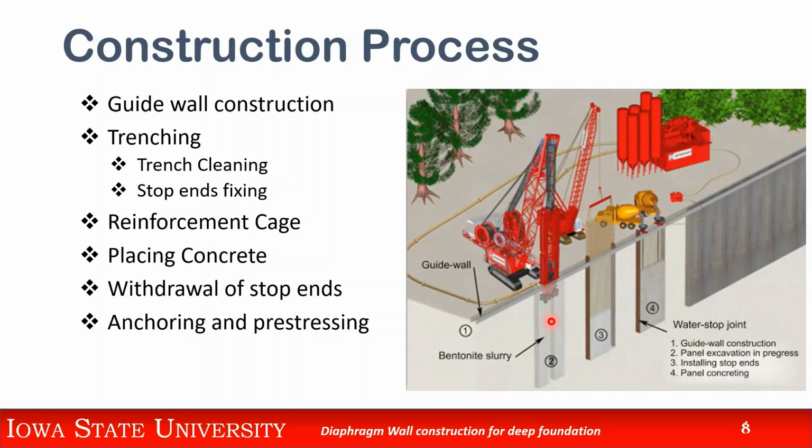Now, sometimes if you have some space, you can lower the groundwater level, which can reduce your problem in terms of taking the water out of it. So if I have some space, or nearly 5-6 meters of space here, I can dig a borehole, lower the groundwater level of this area, and then I can do the excavations. Depending on where you are, sometimes you don't have space for drilling the borehole, sometimes you have. So if you don't have the space, you use a pump to take the water out of the panel directly, and then insert the bentonite slurry.